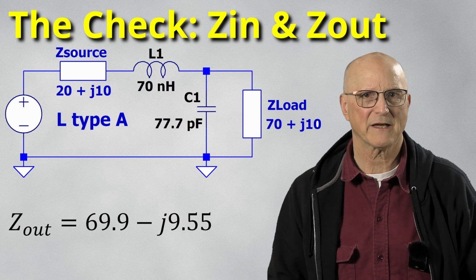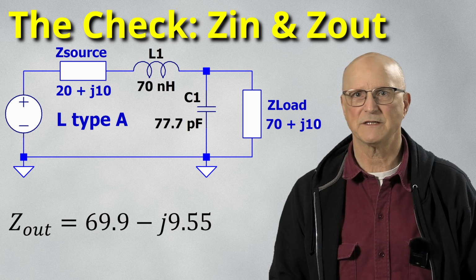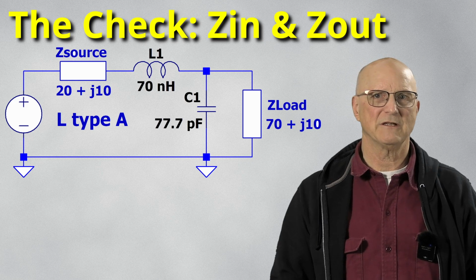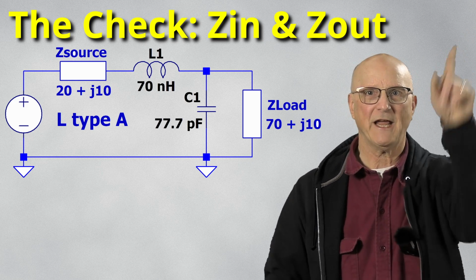This is the complex conjugate of the load impedance of 70 plus J10. Considering that this is arrived at using the Smith chart and our calibrated eyeballs, this is a check and a check. We have completed the first example showing how to design your own impedance matching circuit with an L-type configuration.